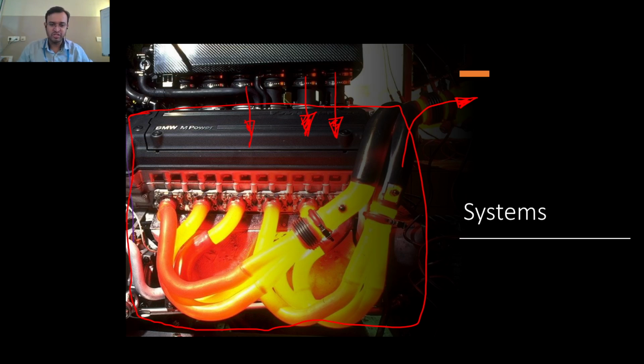At the same time, these red hot pipes are radiating all of this thermal energy, and they are dissipating it to the atmosphere or to the surroundings. So in this problem, you have got mass flow across the boundary as well as energy flow across the boundary. And this thus is an example of an open system.